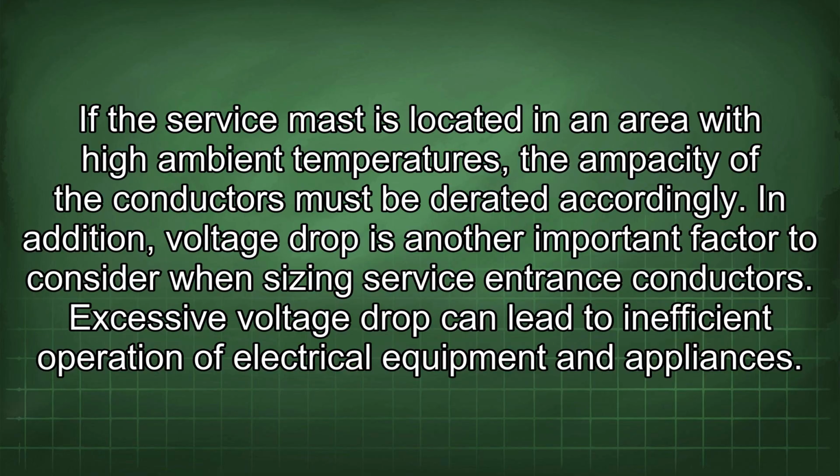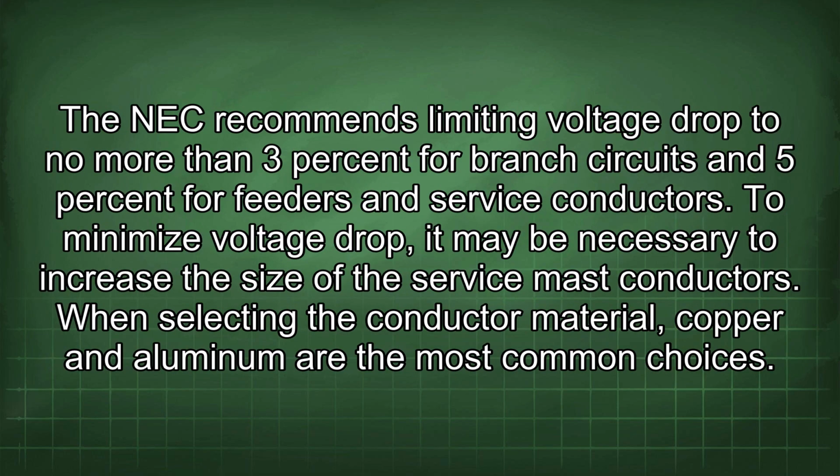In addition, voltage drop is another important factor to consider when sizing service entrance conductors. Excessive voltage drop can lead to inefficient operation of electrical equipment and appliances. The NEC recommends limiting voltage drop to no more than 3% for branch circuits and 5% for feeders and service conductors. To minimize voltage drop, it may be necessary to increase the size of the service mast conductors.